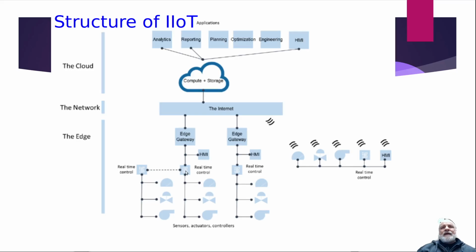And then the PLCs and the HMI can send data through this gateway device on the edge of the internet, and then that edge device or gateway device will pass that information up here to the cloud, where we can store it in a database and do analytics and reporting on it and just monitor the real time actions.